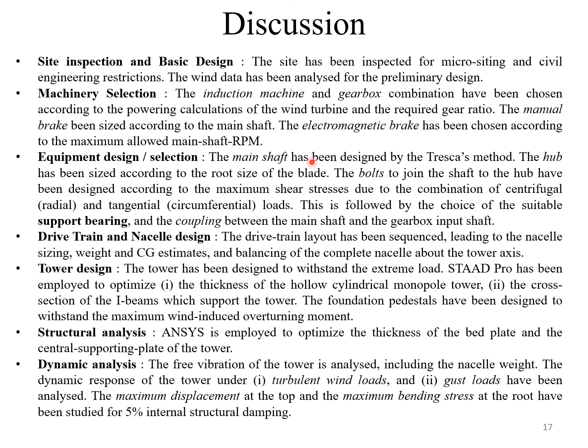A brief discussion of the work done has been presented here. The work started with the site inspection leading to concept design followed by the basic design. The machineries were selected accordingly. The shaft was designed according to various loads on it using the maximum shear stress failure criteria. The bolts were chosen subsequently.